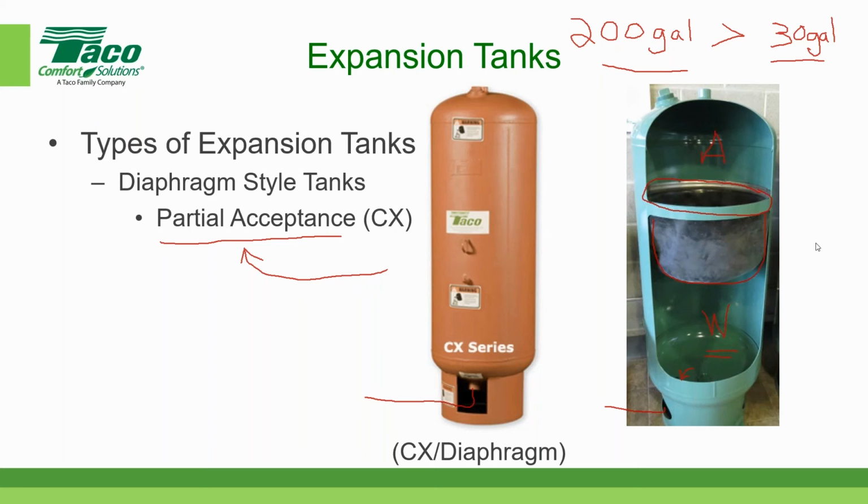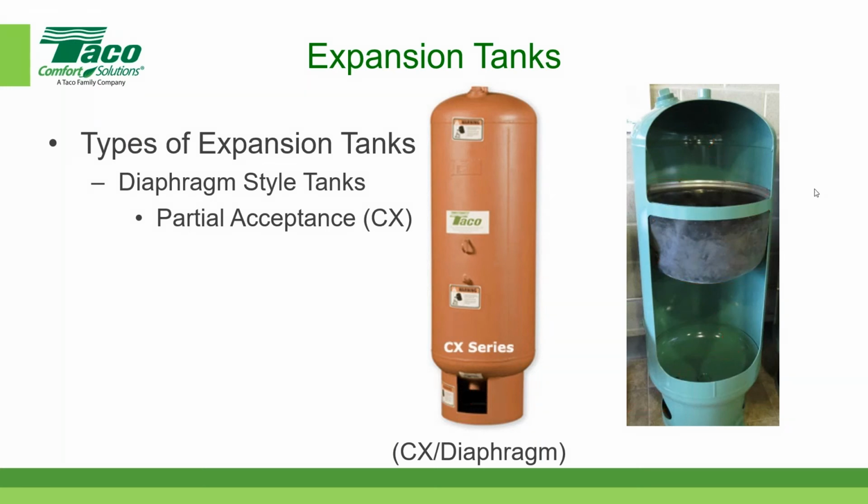So Brett, any questions? Yep, we have a couple good questions. Somebody asked, and you covered it, but I just want to emphasize which tanks have replaceable bladders. The full acceptance, the partial acceptance, yes. Diaphragm, no. It's not really a bladder. As you can see from this cutaway, this tank is a throwaway tank. That's correct. That's what we call that.